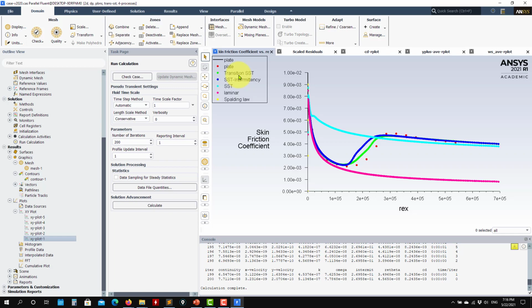You might be able to use eddy viscosity models, but nonlinear eddy viscosity models, to solve this. Also using some very specific LES models, very well calibrated for wall-bounded flows. But if you go to LES, you will need to switch to 3D, so it will be very, very expensive because 3D is also unsteady. Okay, so this is this case, a very interesting case.